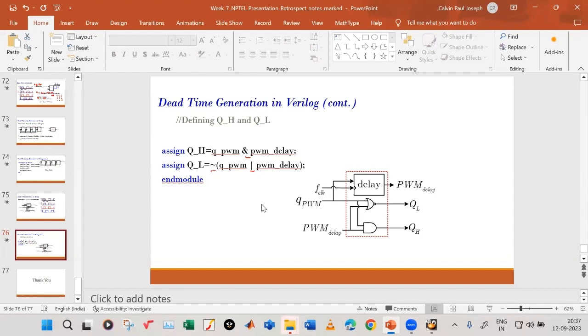No, you have to write the code module, create them one by one, check whether each module is correct, and then simulate it. When you simulate it, you have to give the clock inputs and force some particular constants.